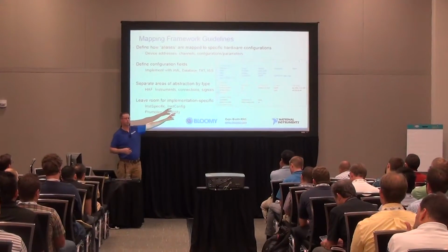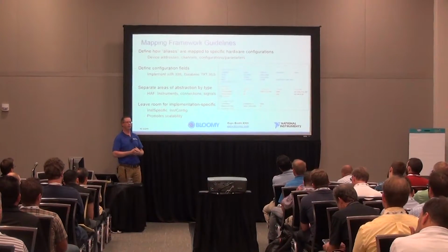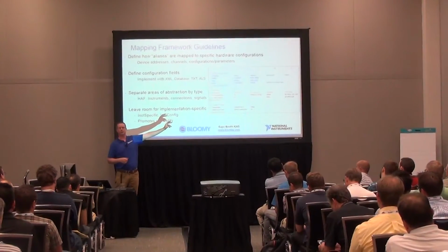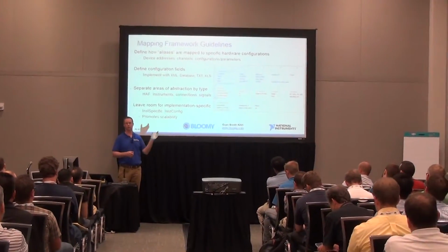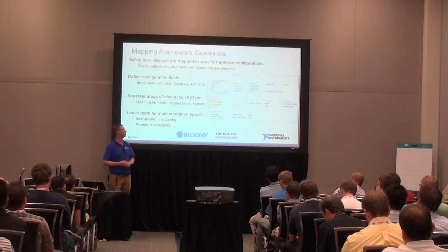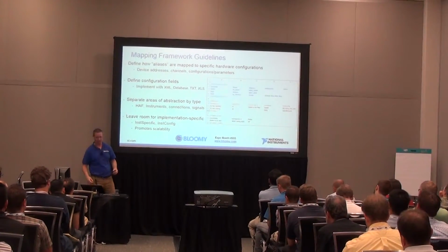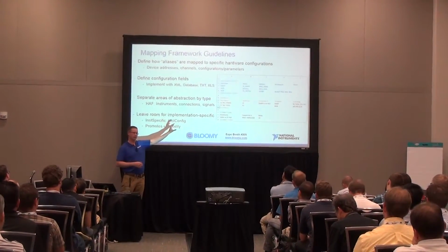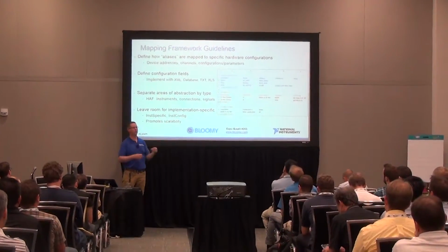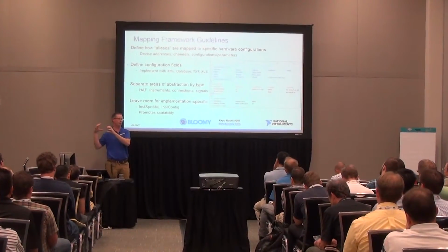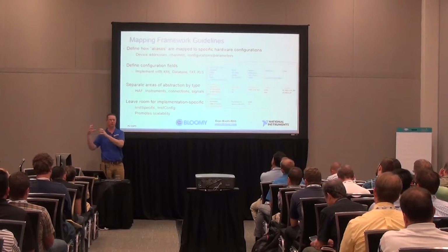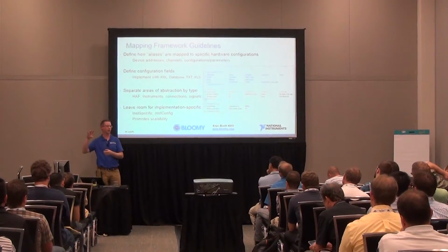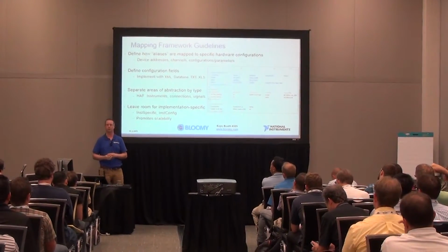And by doing that, the instrument config promotes scalability. If you add a new driver that you haven't thought of or a new device you've never thought of, you can always fill that instrumentation config field with the particular parameters of your specific device. And one of the things that we've done recently is create a configurator for this, so that you don't even edit the Excel. If you choose DMM, it will show you the particular parameters for DMM. If you switch DMM to DAC, it'll show you all the DAC particular parameters. If you switch it to a waveform with a scope, it'll show you all of the horizontal and vertical configuration parameters for the scope.